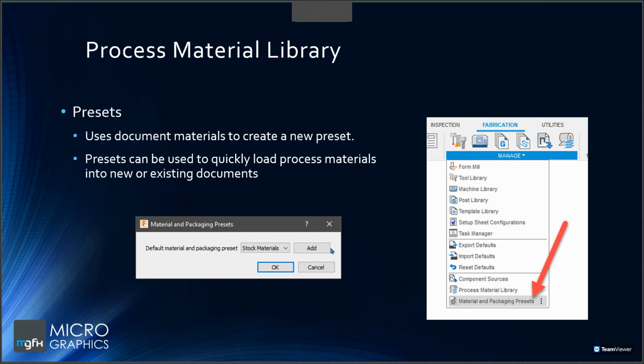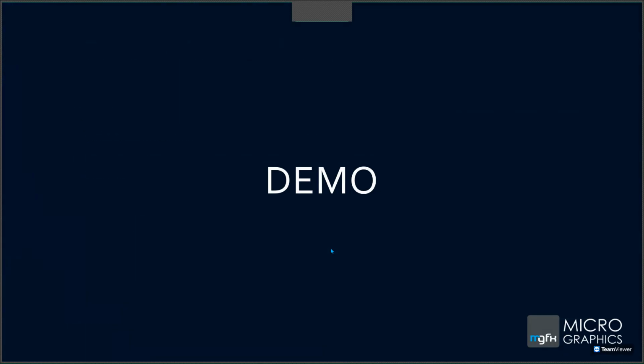So right up front, I would suggest you create a blank design, put in everything that you need or that you stock, and then create a preset. You could also break the presets down. It could be steel only presets. It could be a preset for aluminium only, or preset for wood. And so you can have that preset, and every time you then take a design and nest it, you can load the preset into your material library. Just makes life a lot quicker and easier when working. You don't have to manually go and add in all those line items again and all the settings. So just a little tip there on the presets.